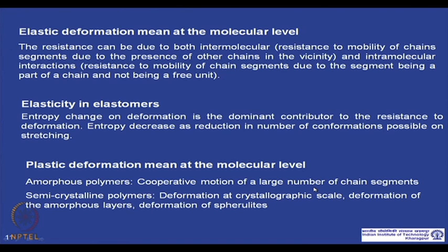Polymer chains might slip in the direction of the applied stress, or move in the perpendicular direction, and there could be deformation in the amorphous region, or in the spherulite region.